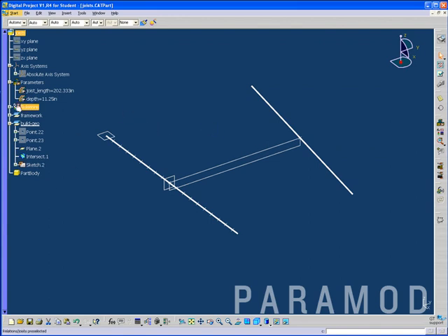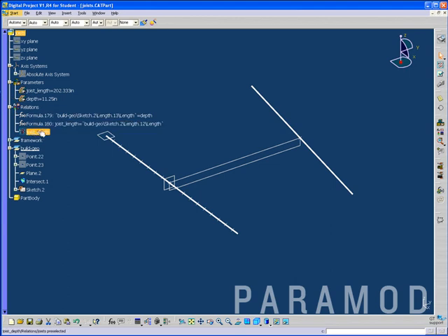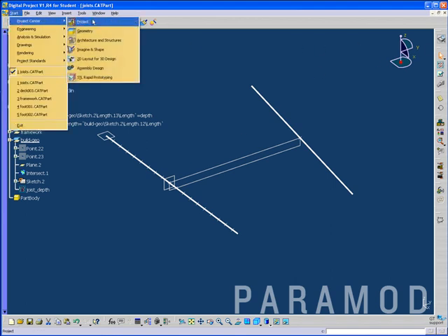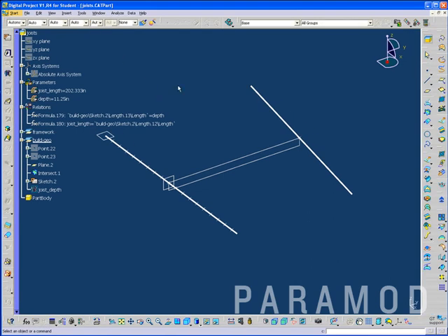And we can see in relations now, there's a new icon, and there's a joist depth rule. So what I'd like to do is just take that and drag it down to our build geometry, so that our rule gets created each time we make a new power copy. And so we can exit the workbench now and go back to Project Center Geometry, back to some icons that we're familiar with. We need to now drive the sketch